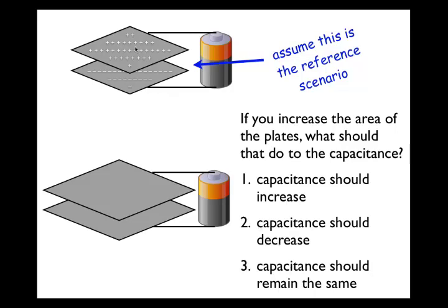So, in order to charge a capacitor, I have to connect those two conducting plates to some sort of power supply. So I've drawn a battery right here. And you can think of a battery in this situation as a charge pump. It's going to pull electrons off of the top plate, send them through this system, and deposit them on the bottom plate, and that will make the top plate become positive and the bottom plate become negative. And it'll keep doing that process until it can no longer add additional charge to the bottom plate.